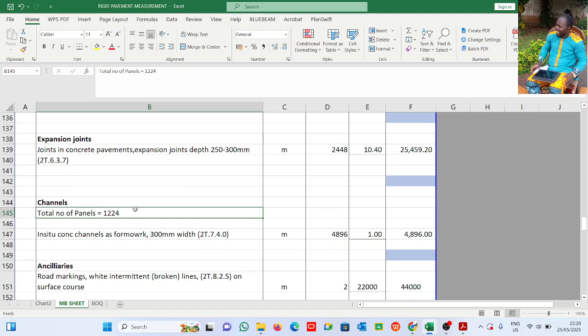Channels give you straighter edges compared to formwork, and it's difficult for it to sag, it prevents honeycombs, one, and it does not bulge with pressure. All right, so channels are used.